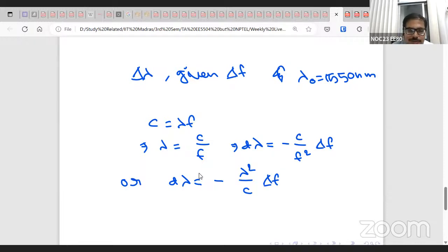So the question was based on how much the wavelength changes given a particular change in laser current. From the current, you have to find the change in power. This you can get from either the slope efficiency or the long equations that were given. So from current, you can find the laser output power. And using that, you're supposed to find the chirp, that is the change in frequency.